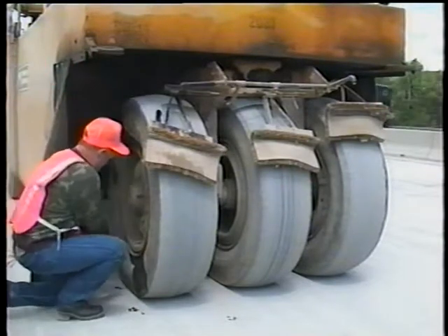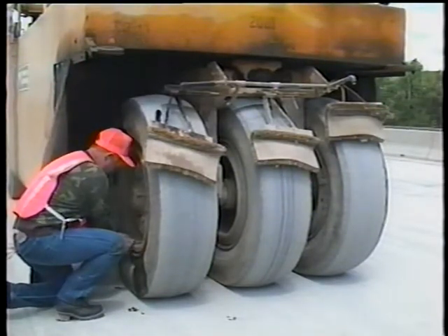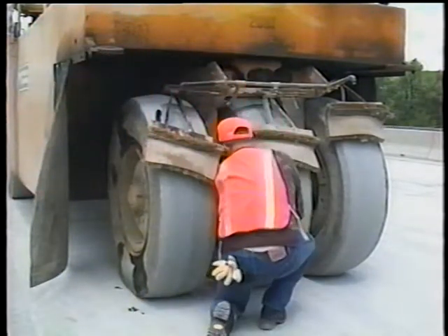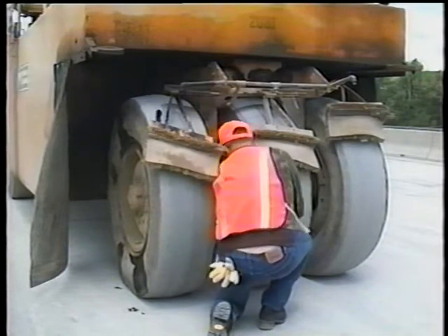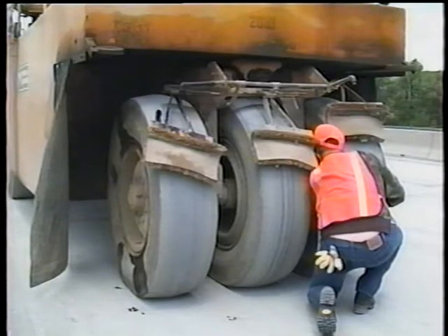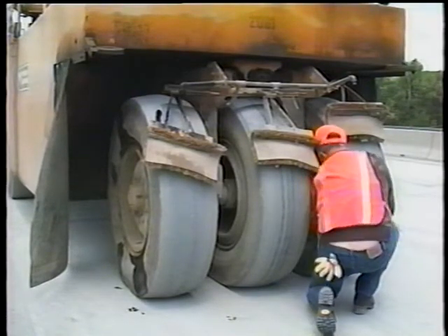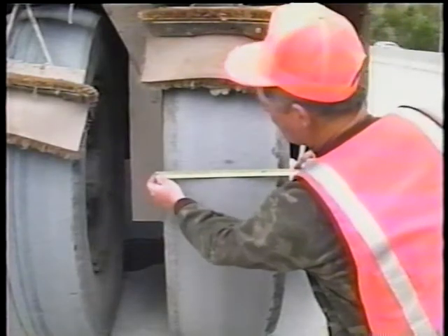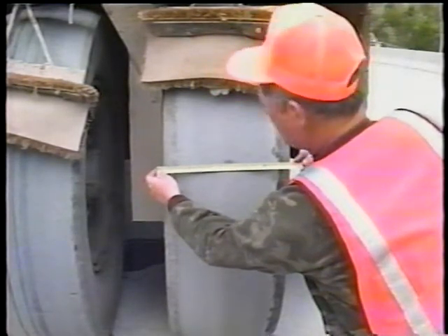Now let's look at pneumatic tired rollers. Tire pressure greatly affects the performance of these rollers. All tires must be inflated to the same pressure within the tolerance suggested in the checklist. In addition, these rollers should have a working weight capacity of at least 115 kilograms per 6 centimeters width of tire tread. So measure the width of the tires and divide the number of centimeters into the total weight of the roller. Your checklist covers these calculations in detail.